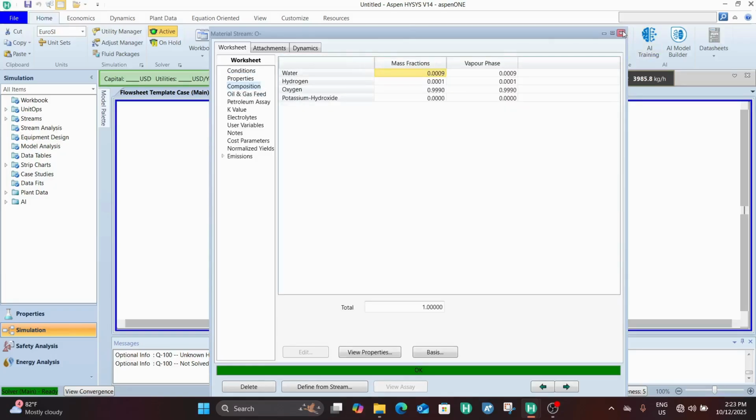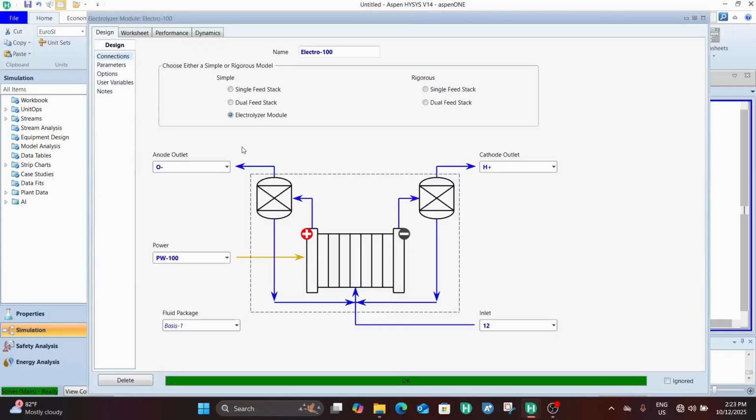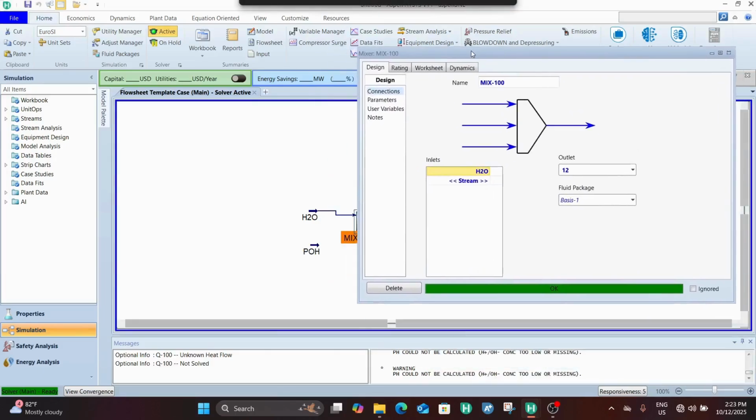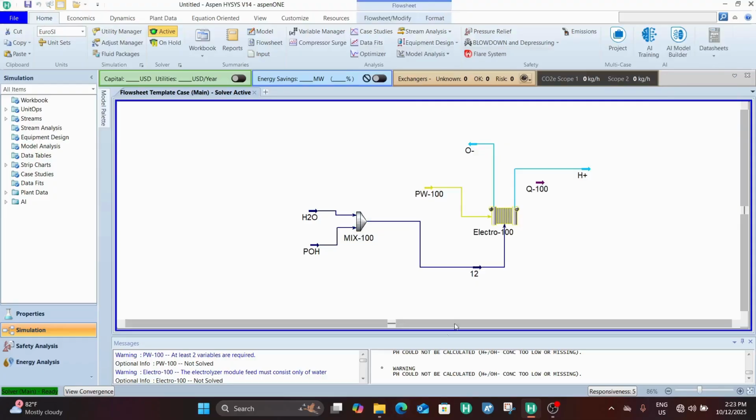So the purities are intact, and this is where our electrolyte stream that we left in. Some of you might be thinking, why go through the stress of recycling that we did for the alkaline electrolysis if you could just use this inbuilt gas liquid separator and it would just do the whole recycling for you? So this is where I need you to take note of something very important. We're going to plug back the electrolyte, even though it's a PEM electrolysis, we're going to plug in the electrolyte, which is potassium hydroxide. And as you can see, it just messes up our electrolyzer.